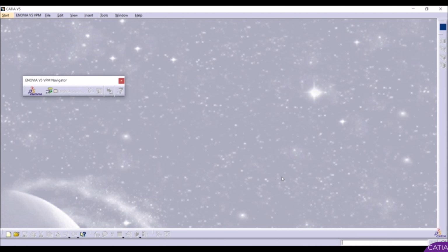So in this case, we're going to create the assembly file first, and then in the assembly file, we're going to create our parts. So in those cases, we will define correctly how one part will fit another part. Because with the bottom-up method, you're not sure if one part will fit with another part until you insert those parts in the assembly. And with this method here, we will see if one part will fit another part more easily.